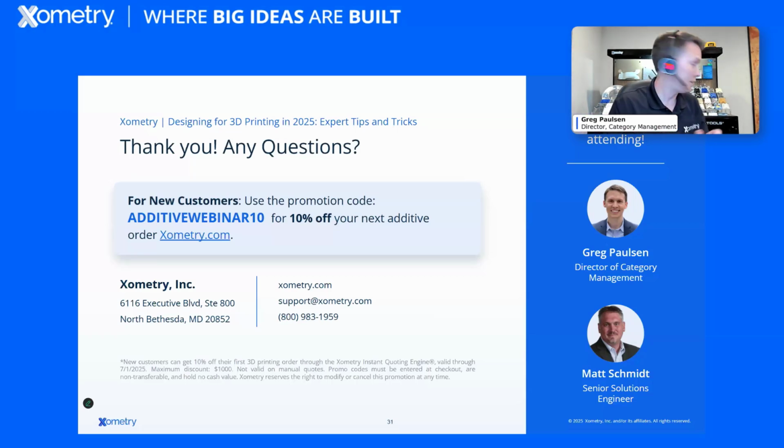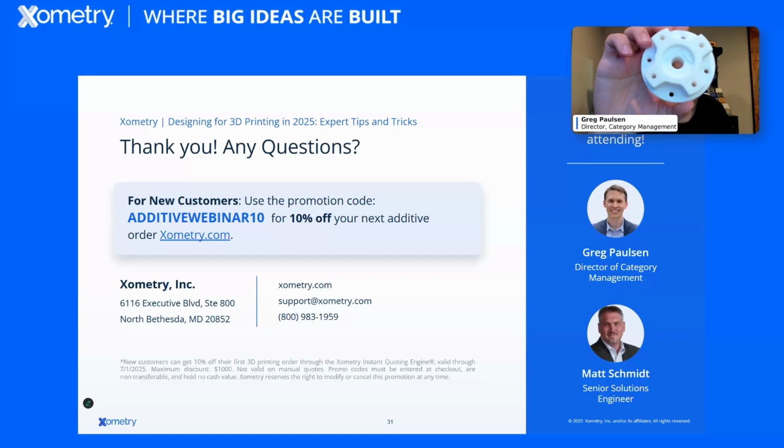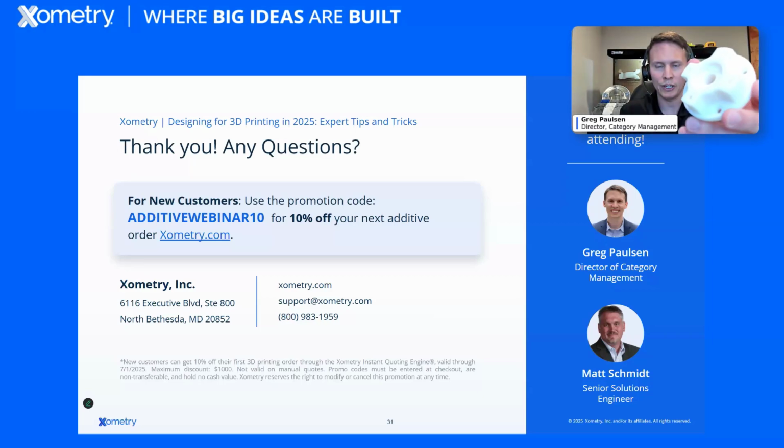But a bread and butter everyday use, which I actually have stacked right behind me, is ceramic filled resins for stereolithography. All of these auto quote on the Xometry site, and they are really good for test jigs and fixtures. If you're doing wind tunnel testing, for example, don't expect flex, but expect very, very high stiffness. So I have Accura Bluestone here. I have Formlabs Rigid 10K. And then I have Somos Perform.